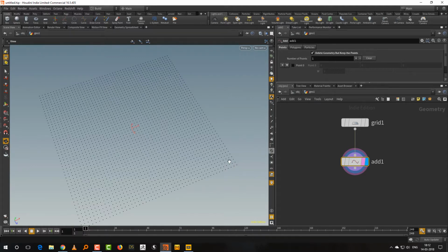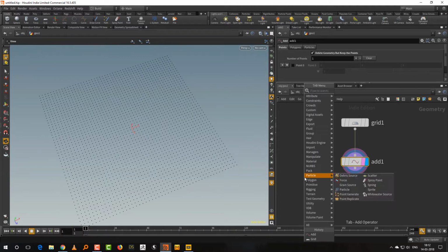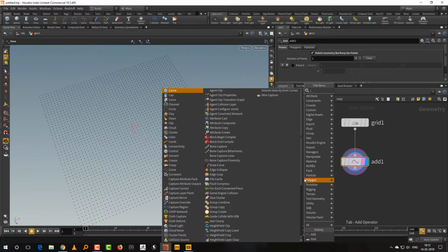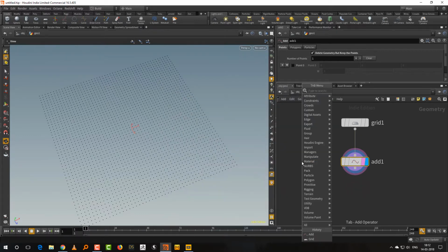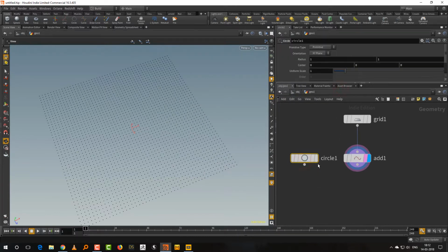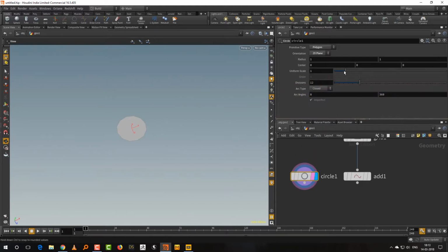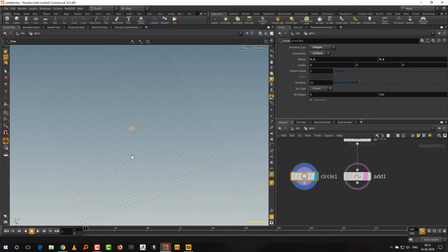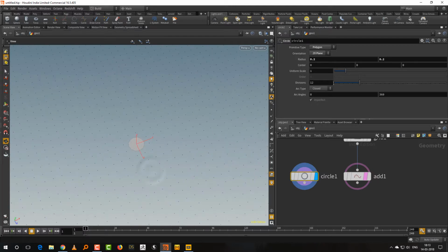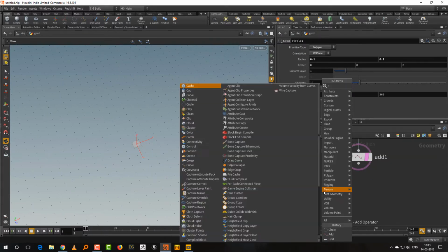The next thing is I want to copy some circles on this. I want to copy like a cylinder. So let's take a circle, and I'll put it in the ZX plane. Let's keep it to polygon, and I will make it small. So how big is this? No, smaller still. So let's go to 0.1. And let's do a copy.